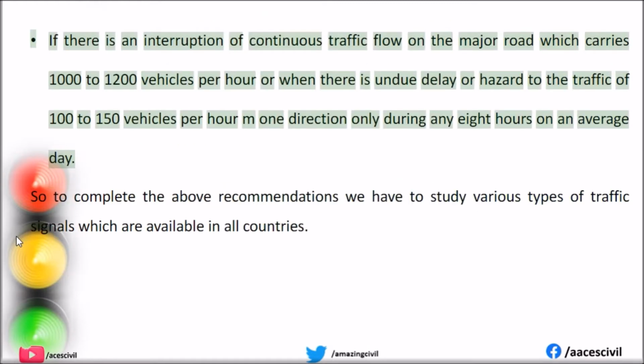If there is an interruption of continuous traffic flow on a major road which carries 1,000 to 1,200 vehicles per hour, or when there is undue delay or hazard to traffic of 100 to 150 vehicles per hour in one direction only during any 8 hours on an average day.